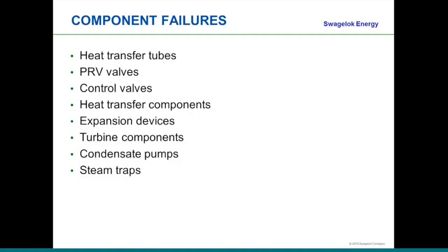We must stop them from going into critical operation, and we must install correctly and select the components. Control valves: again, installing control valves correctly, making the correct selection. Do I use a cage, trim valve, globe? What does the internal look like? How do I operate, electric or pneumatic?